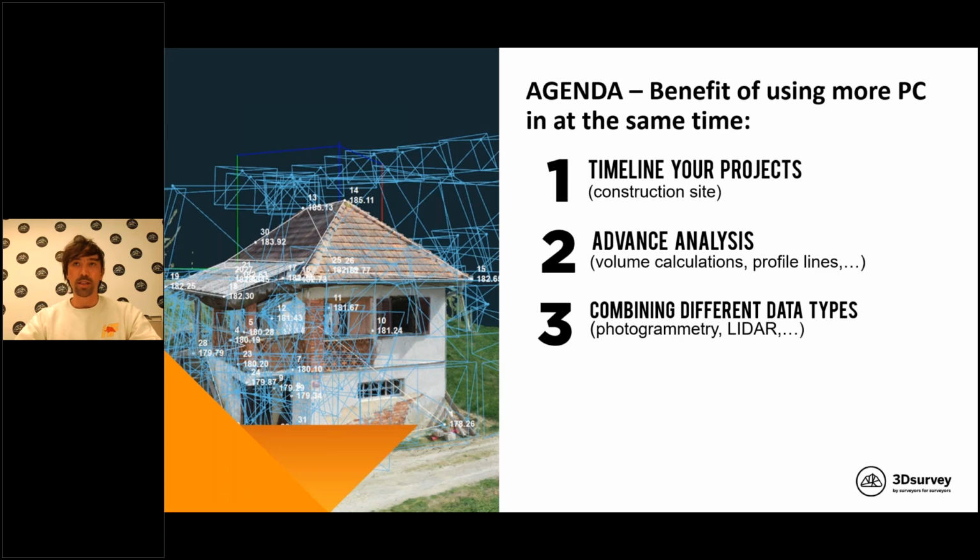We all know that with photogrammetry, if you have a tight forest with big trees and everything like that, it's hard to get the terrain points. And if you really need a terrain point, you need to combine it with a total station, measure some additional points, or if you have the option, use LiDAR data, which penetrates the vegetation area.